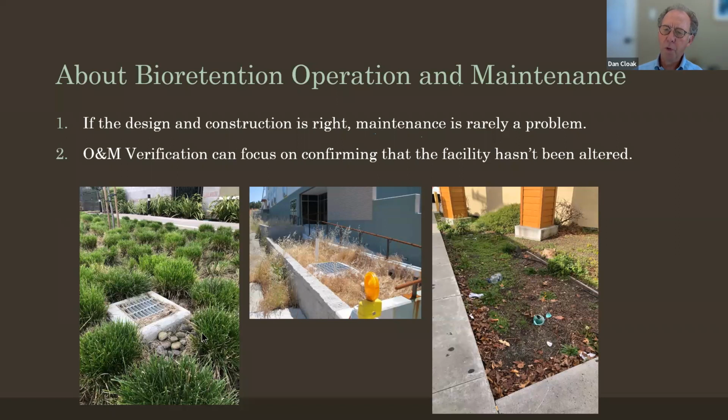But the reason that happened is that this is at the down gradient end of a large bioretention facility, and the runoff came flowing across it, and it accumulated down here, and it filled up, ponded on this end, where the total pond volume is relatively limited because the whole thing is sloped, and the accumulated vegetated material, which had washed down, then washed into the grate. Not the worst thing to happen. Most rainfall falls in storms that are smaller than this one, but it just shows that, well, if it had been built flat, not a maintenance problem. It wasn't built flat, not a lot you can do about it.